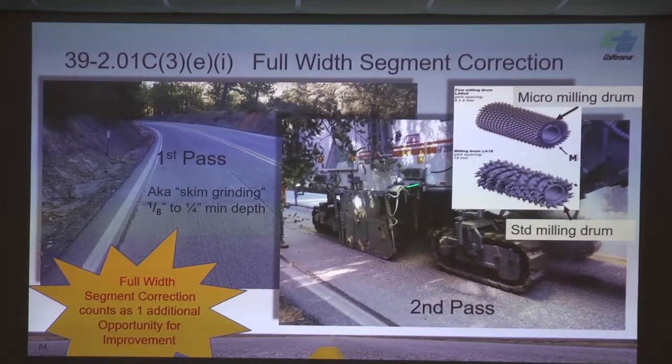Yeah, so these cold planers basically have sonic sensors on them. I think some of the older ones had a physical ski, though I've never seen one. They're designed such that the cold planer is going to try to cut as smooth a plane as possible. If the tracks are going up and down on the grade, and it goes over a bump, it's going to want to lower the grinder head a little bit. Did I get that backwards?